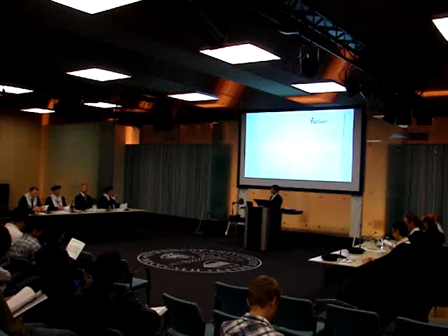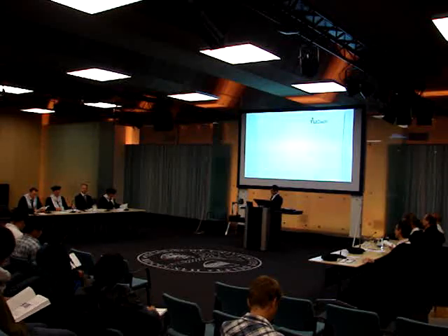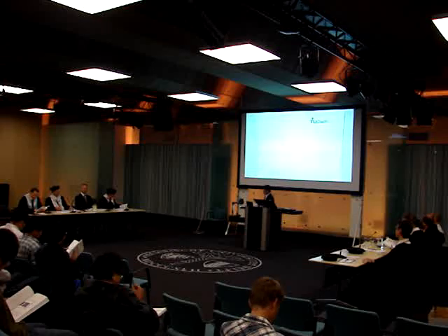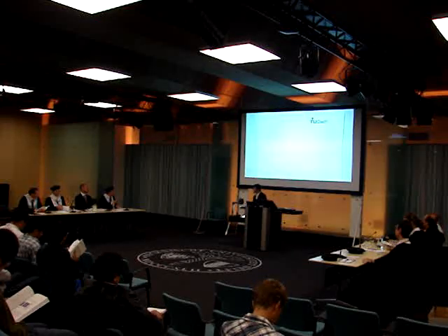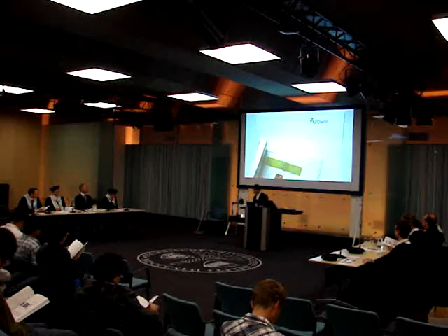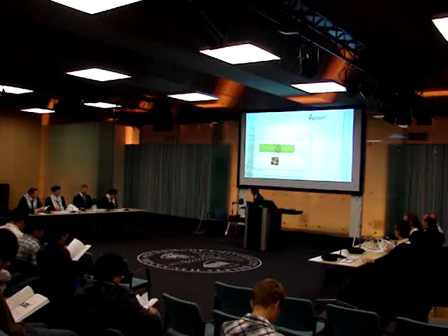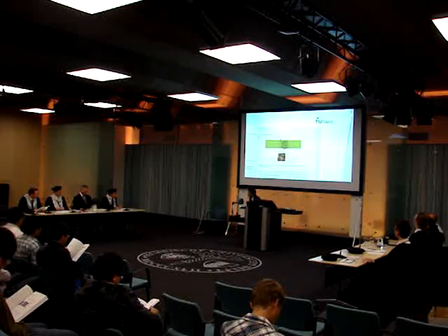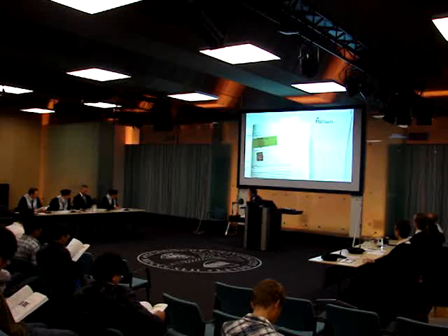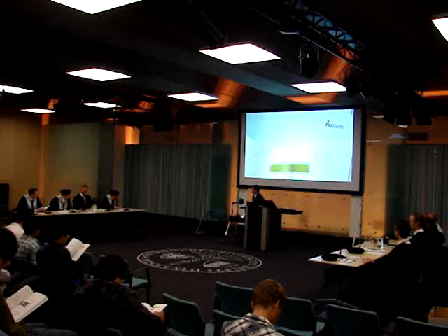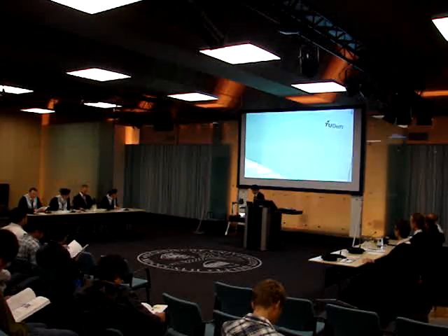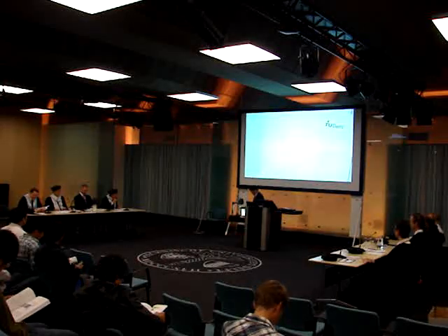This is a complete beam with a discrete crack, and you use one level deeper, so to say, for the micro behavior. And you use a number of material properties there, which are kappa, gamma, beta, and the so-called C, which has something to do with the width.